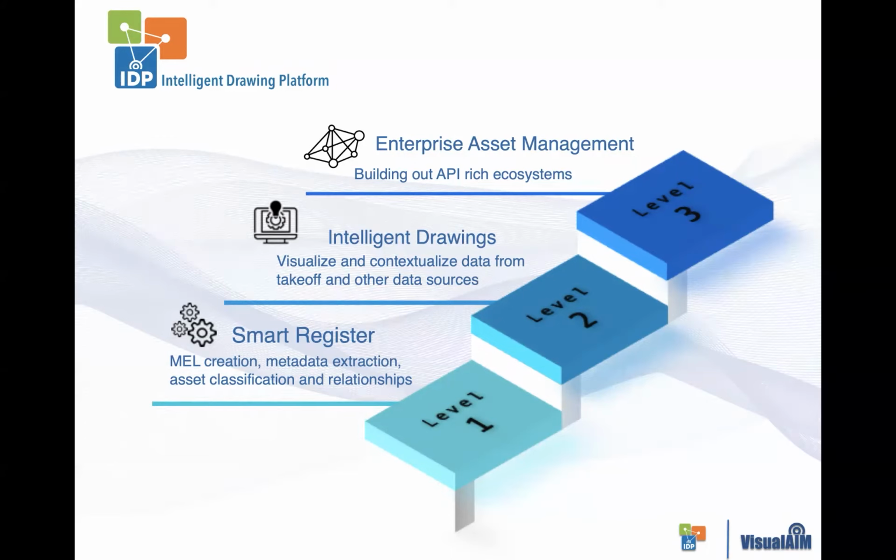It could be an inspection data management system where we have CML readings and thickness, T-min calculations and thickness readings inside of it. We could pull that information from those external sources and actually visualize it directly on the drawing, either with data pods or, again, re-visualizing by coloring or highlighting certain parts of the drawing.